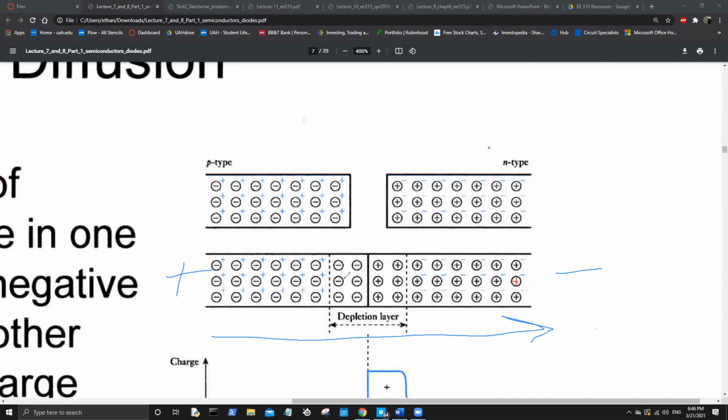Because if you were to only touch the P-type and N-type of the silicon and have no excess biasing on the system, such that both were completely in contact with each other everywhere, it would just become intrinsic again. Fundamentally, it would neutralize and become intrinsic. But the second you put an excess charge across, it breaks this equilibrium and allows charge to flow normally again. And that's how the PN junction operates. So by adding an external bias on this stable system, if you leave it how it is, it stays depleted and charge will never flow.